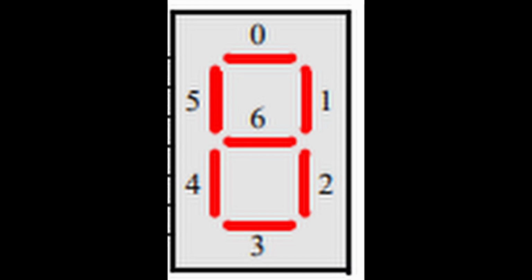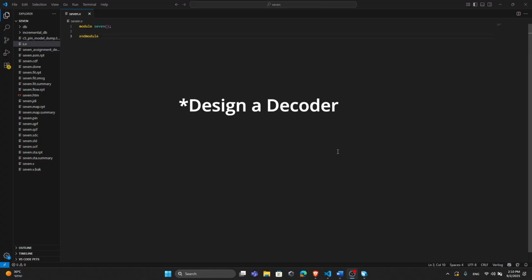So, the 7-segment displays on the FPGA are common anode, which means they don't work like a normal LED. On these displays, a signal of 1 means off and 0 means on. That is called active low logic. To display numbers, we just choose which segments are on or off. For example, if we want to show 0, we must have all the segments on except the one in the middle.